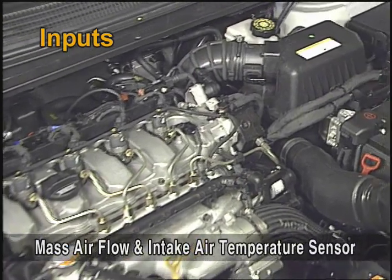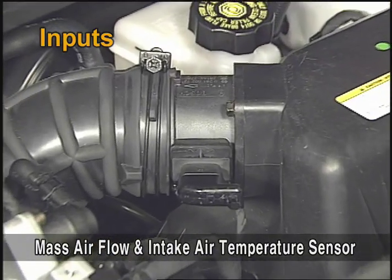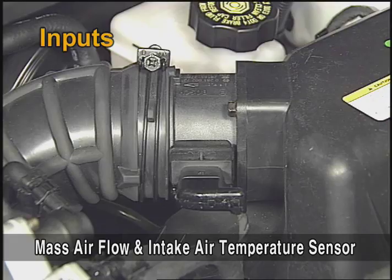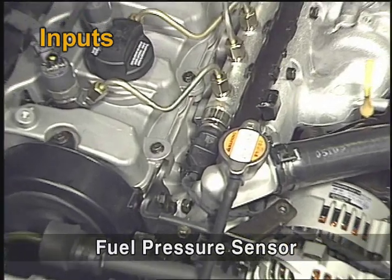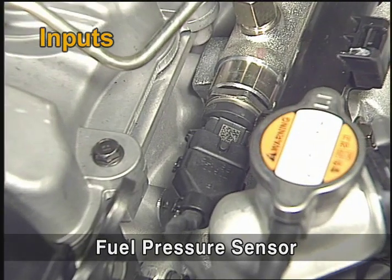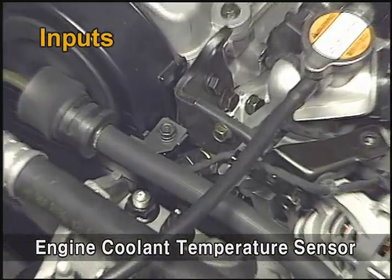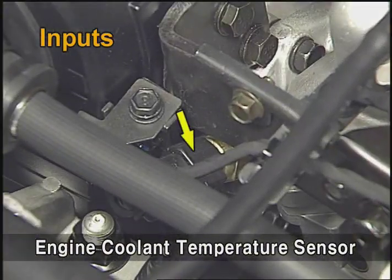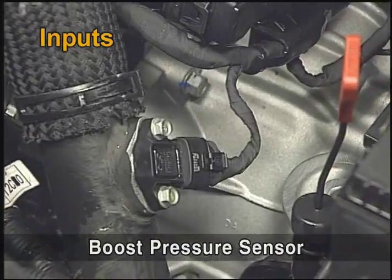the accelerator position sensor 1 and 2 for detecting the driver's driving intention, the mass airflow sensor and the intake air temperature sensor for detecting the amount and temperature of the air inflowing into the engine, the fuel pressure sensor detecting the fuel pressure and sending it as the fuel pressure feedback signal, the coolant temperature sensor for detecting the coolant temperature,